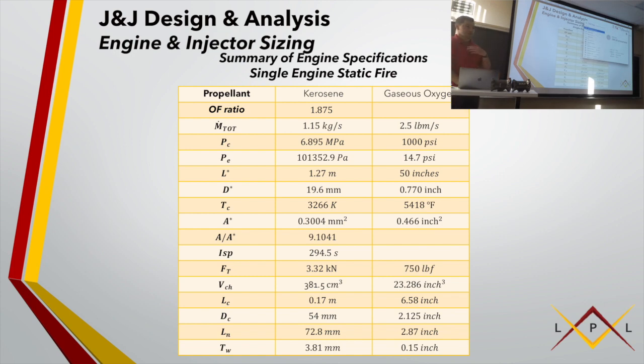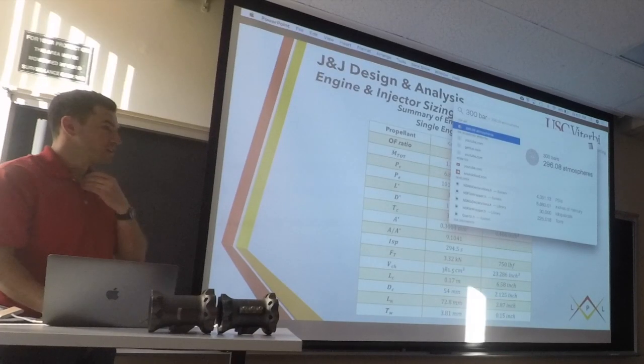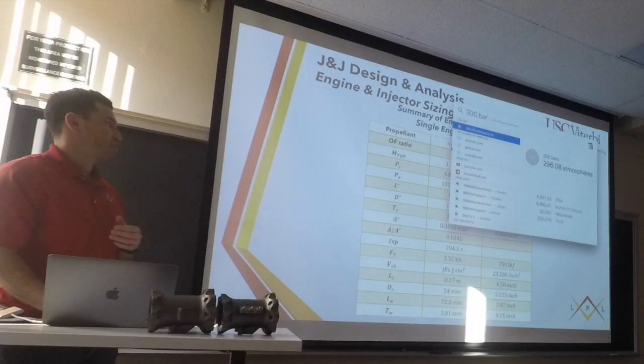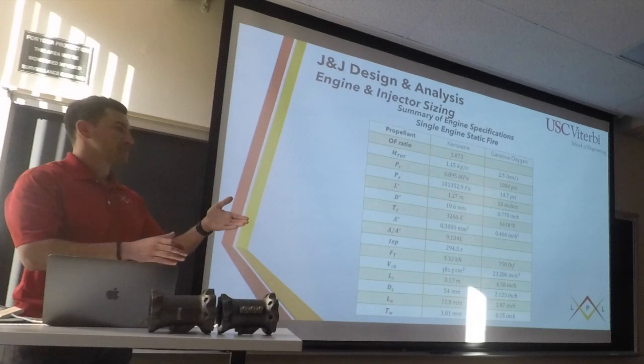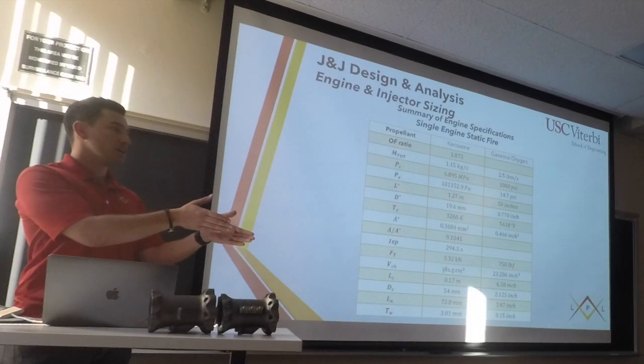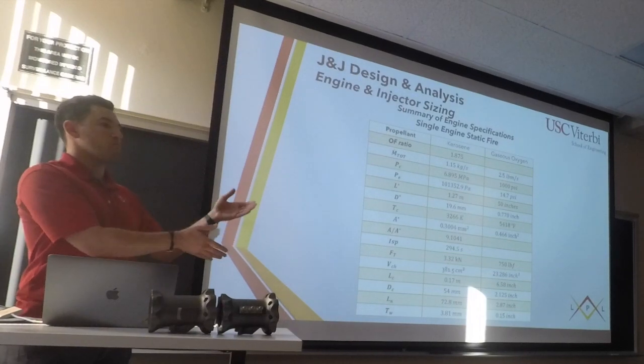4,300 psi in the chamber, which is, I think the SSME is the highest one right now with like 3,000 psi roughly. So it's another 1,000 psi. So it's a high pressure, and the tanks are very near atmosphere. So then all of a sudden it's like, well, now we need an extra stage. Well, now it's going to add a lot of mass, so we don't have room now for it.